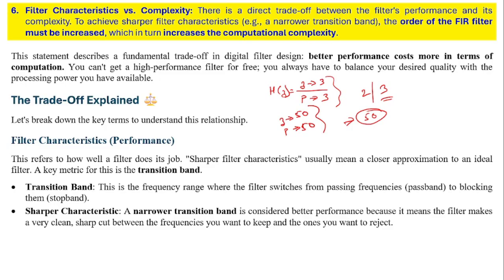So in IIR filters, in the pass band and the stop band, you will find the ripples are quite higher. Computational complexity will be smaller, but you are deviating from the idealness, because you will be having more ripples in the pass band and the stop band.